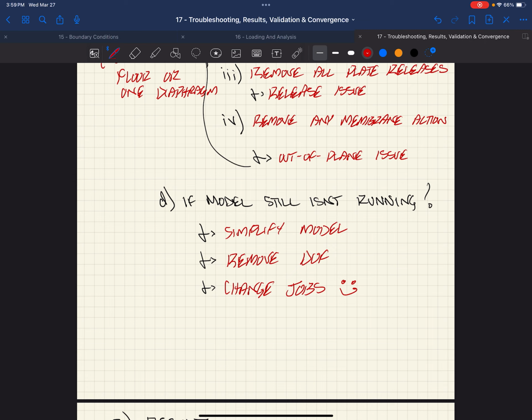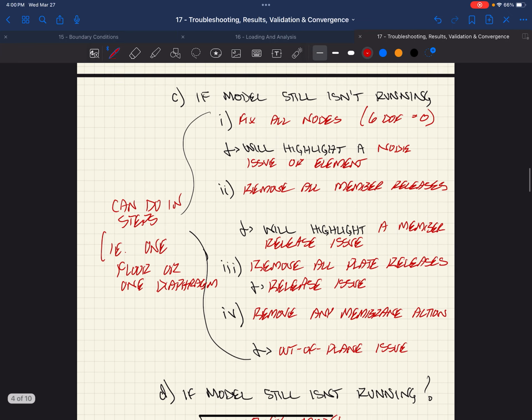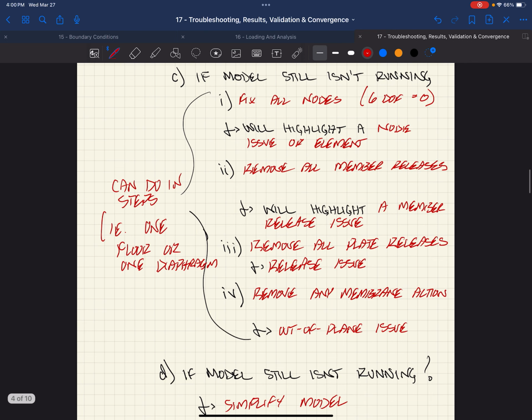We're going to talk about validation here, but it's important that we understand fundamentally, or have an idea of what the behavior of the structure is going to be, based on our analysis. And so we can do that by simplifying the model and making sure that it meets our gut check. And sometimes just meeting some of our rudimentary validation techniques, looking at statics, looking at displaced shapes, things like that. So anyway, it's not all pain, but sometimes it can be painful to get these models running.